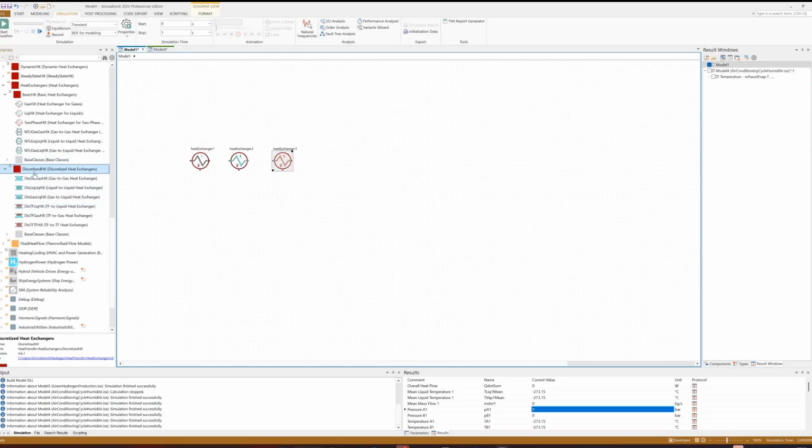Now we are going to discretize heat exchanger models. You already know three models with one-phase flow, and in the new version we also introduce three new models with the possibility of two-phase flow calculation for each interface correspondingly. For example, we have a version for two-phase flow on one side and liquid on the other side with hydraulic interfaces and thermofluidics interfaces, with thermofluidics on one side and pneumatics on the other side, and also the heat exchanger with thermofluidics with a two-phase flow on both sides.